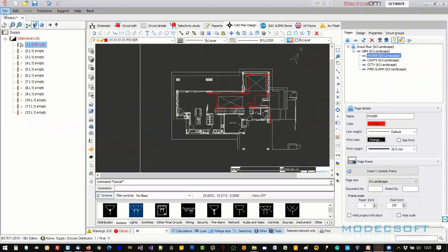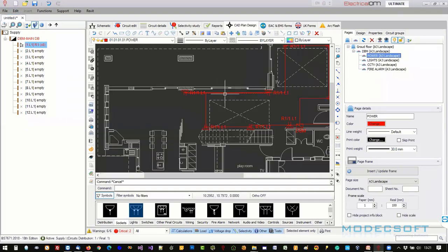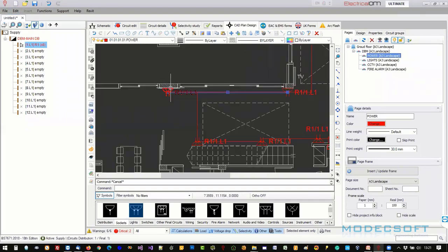They should be locked to the symbols. Are you aware of anything with that? Can you repeat that, please? Because yeah, it seems that they've been putting wires in between symbols, but when editing or trying to move them, it seems that the cables aren't staying locked to the symbols. So the cables are independent of the symbols, okay? Yeah. So if I move this guy, the cable will not move. I have to manually move it.